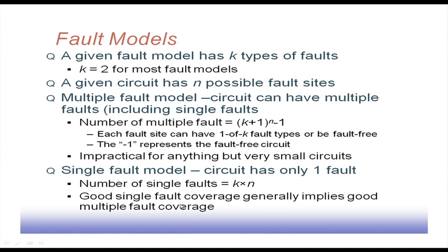This is some experimental result that shows that even if you do not use a multiple fault model, where a circuit can have multiple faults, and you use the single fault model and generate the test pattern set with it, that particular test set can also be applied for multiple faults, and it gives a reasonably good level of detection of multiple faults as well.